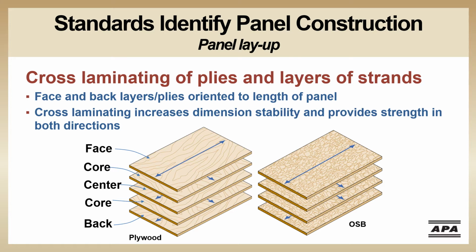All of the veneers are bonded together with a moisture-resistant adhesive under heat and pressure. This creates a panel where the veneers work together to form an integral unit. In this depiction of plywood, there are 5 plies and 5 layers. Again, two adjacent plies with the same grain orientation make one layer, so a 4-ply panel always has 3 layers.